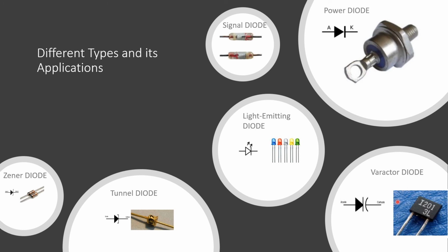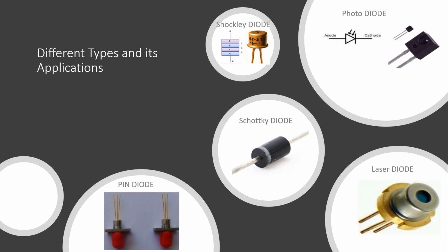So, a varactor is a diode that always operates in reverse bias and is doped to maximize the inherent capacitance of the depletion region. The depletion region acts as a capacitor dielectric because of its non-conductive characteristics, and the P and N regions are conductive and act as the capacitor plates.